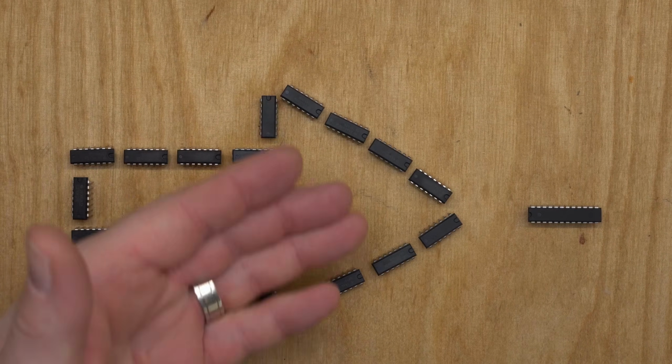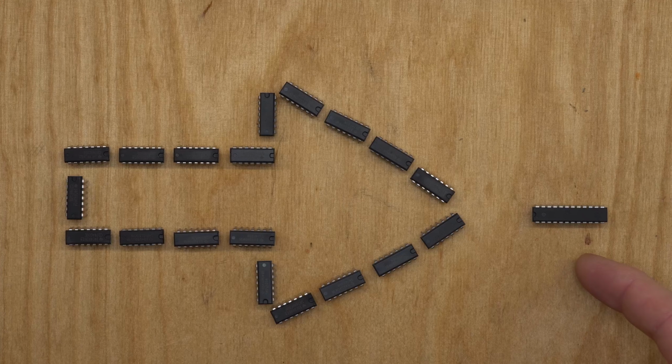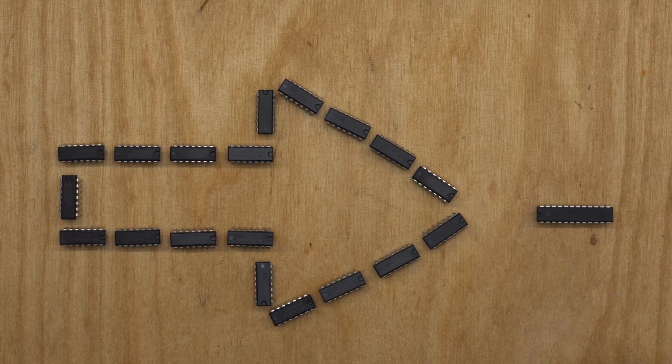A single PLD can replace a shocking amount of discrete logic. Decoders, gates, multiplexers, small state machines, and it keeps the board cleaner. One chip, one program, and yes, one very efficient place where mistakes can hide. In this build, PLDs handle address decoding, I/O decoding, wait state requests, clock stretching, speed control, and eventually interrupt logic. What used to take 20 or 30 TTL chips now fits into a few programmable devices, and still I can reprogram them later.